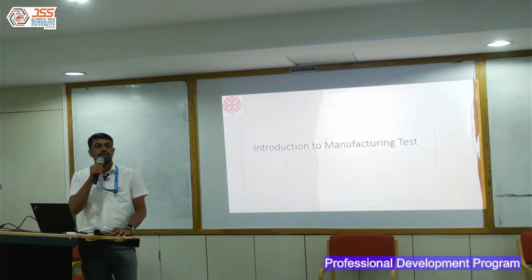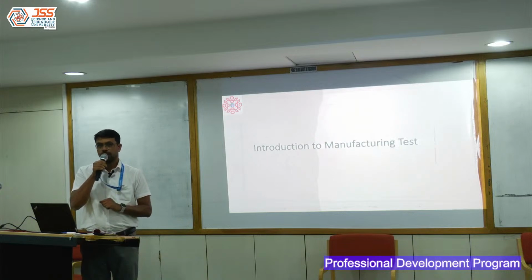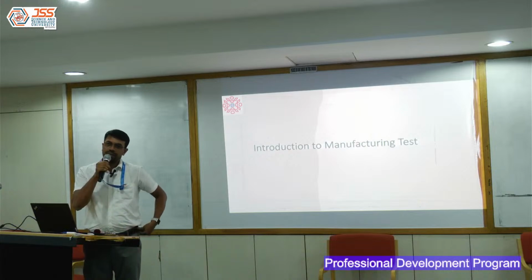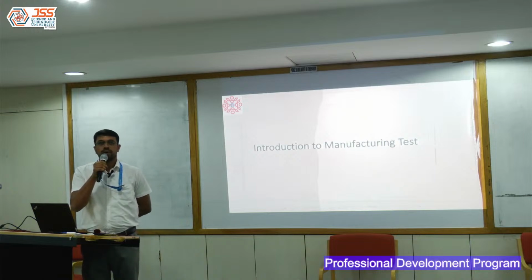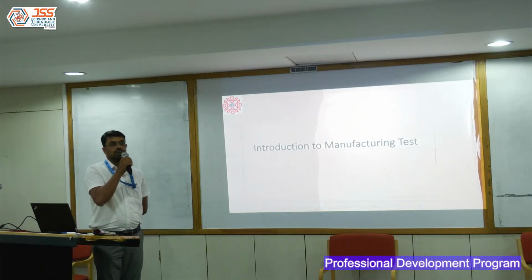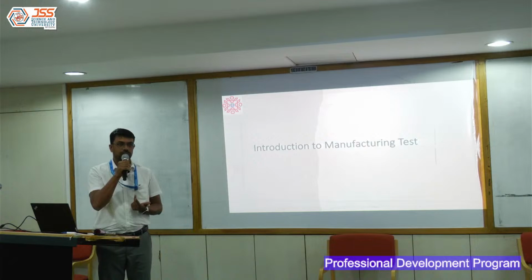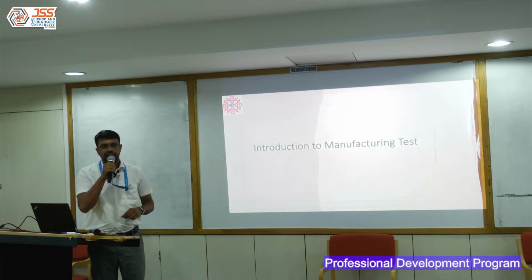DFT stands for Design for Test. Nowadays, they have retermed it as DFX, where X is DFT, Design for Test, DFD, Design for Debug, and DFM, Design for Manufacturing. So my involvement in the design starts with RTL and ends all the way till NPI. NPI stands for New Product Introduction. So if I'm coming up with a new chip, it starts with the requirement spec, RTL, and finally ends with the product being introduced into the market.